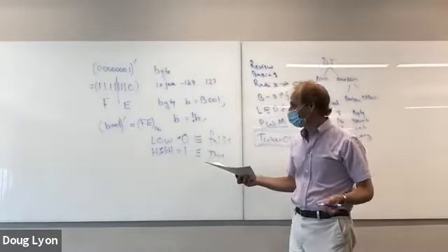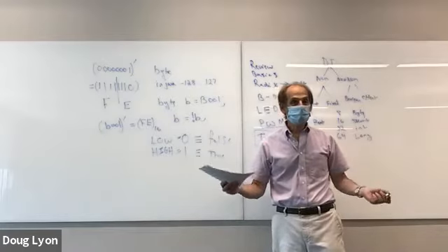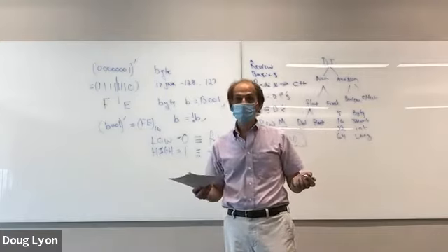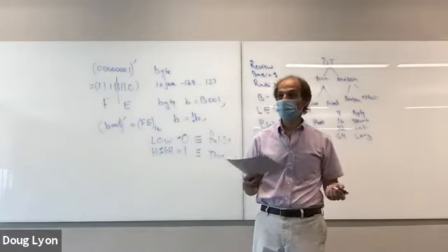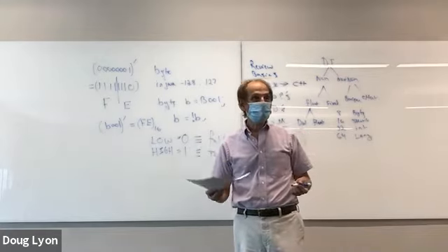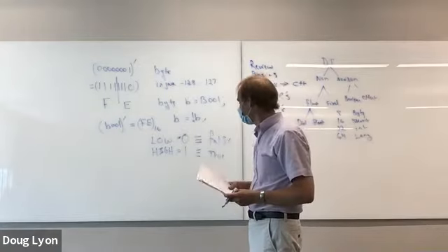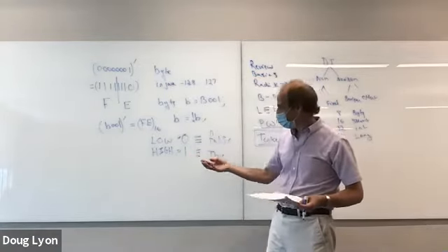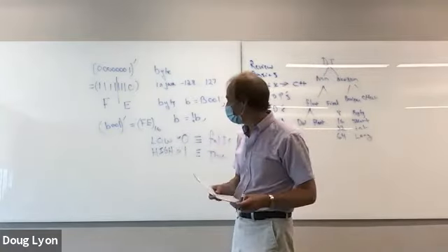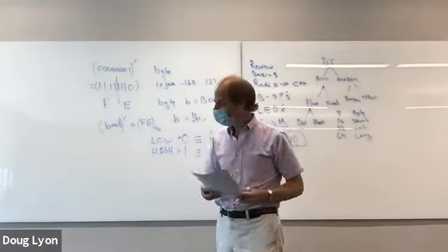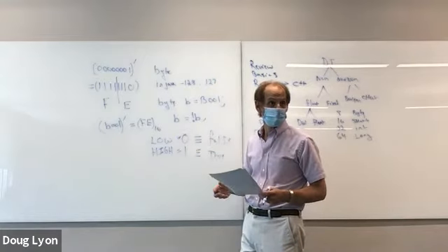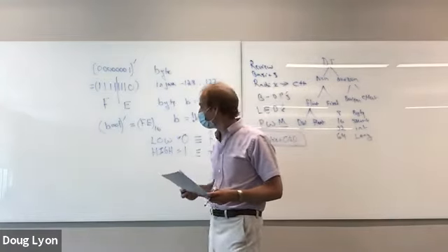Because now, all of a sudden, using 0 and 1 made it easy to see patterns for LEDs. So we knew when the LED was on and when the LED was off. Writing digitalWrite with 0 and digitalWrite with 1 out to a port, it was very clear the LED was turning off and on, 0 and 1. So I kind of like 0 and 1. I don't like to have to write out low and high. It makes the patterns a lot easier to recognize if you're trying to muck about with bit flipping. And that's what this is going to be used for: bit flipping, things like turning your binary lights on or off.